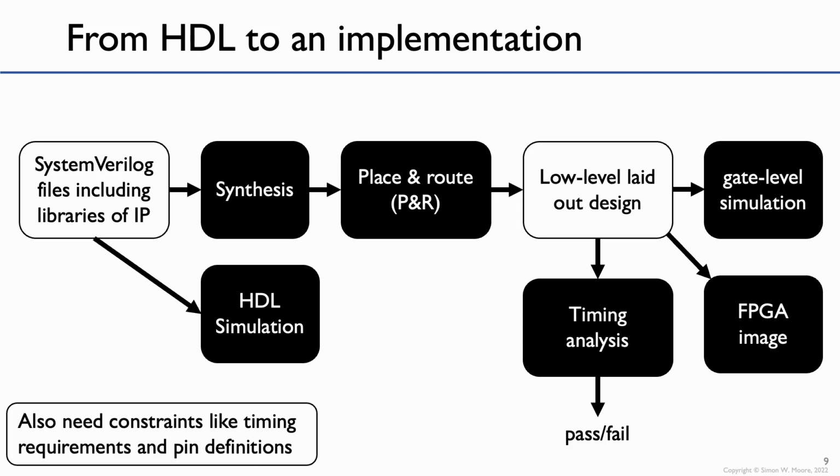And if it realizes that signals aren't going to be used because they're not connected to any physical output pin in any way, then it'll just optimize it away. And so you can find out that if you don't have a pin constraints file, your entire design gets optimized to absolutely nothing, which is nice and compact, but doesn't do anything useful.